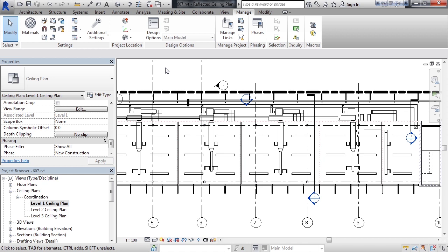And then we discussed the top plane as it resides above the ceiling, how the cut plane controls what you visually see within the actual ceiling plan and what you visually don't see within the ceiling plan. And lastly, we defined the depth, where you can see an additional amount of space or distance above the top plane if you choose to set the depth.